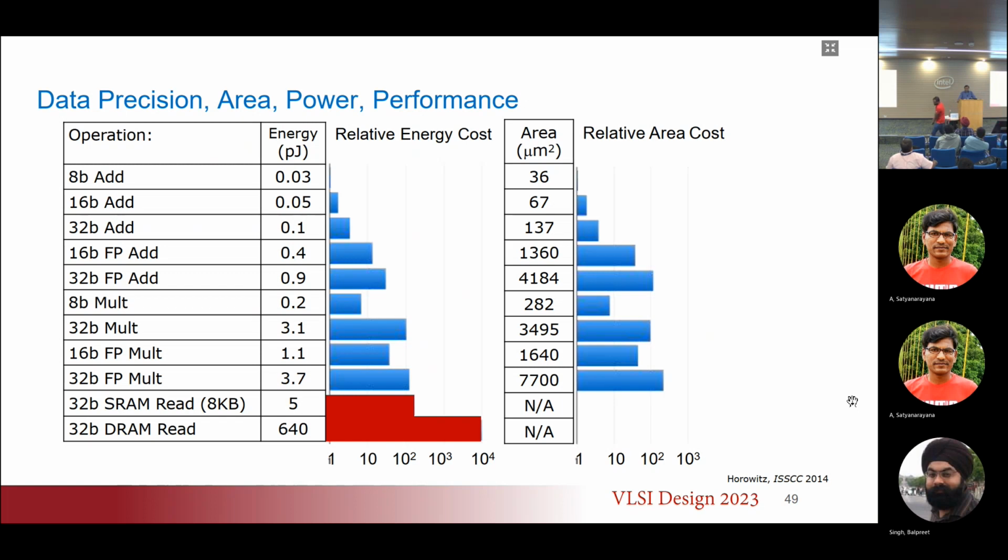The SRAM has very high reliability. We are not concerned about the reliability of SRAM. If SRAM has poor reliability, then we might as well exit the semiconductor business. DRAM also has fairly decent reliability. Only when it comes to something like flash memory or resistive RAM or things like that, then we have limited reliability. We can do a limited number of reads and writes, typically about 100,000 writes. We can all use SRAM, but there's a cost.